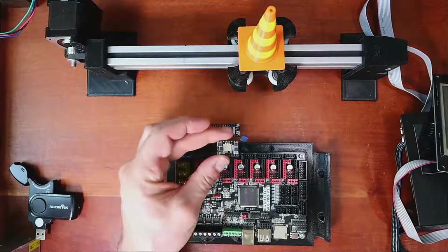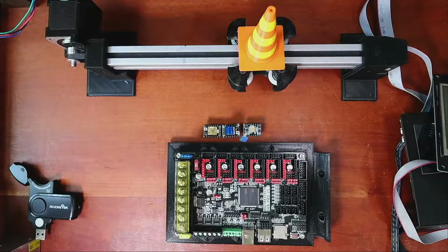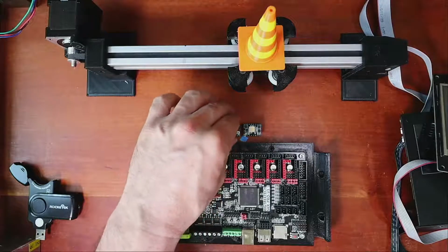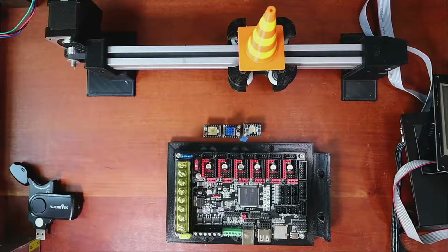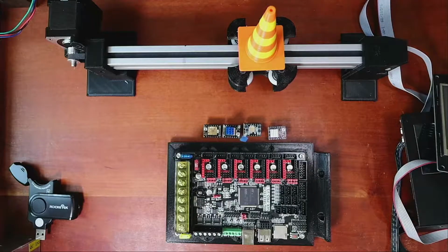Then they make a stronger stepper. This is a TMC5160, and this will do higher amperage, I believe, or current, we'll say for now. I have more here. I just have to find them one at a time. So there's another type of stepper that does step dir. It stands for step direction. And a DRV8825 does that.